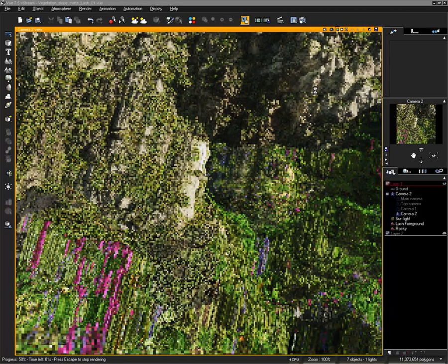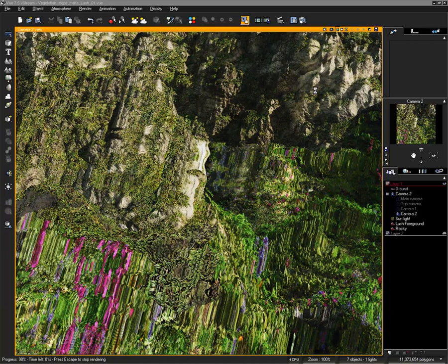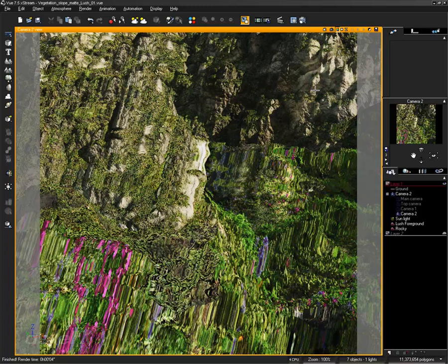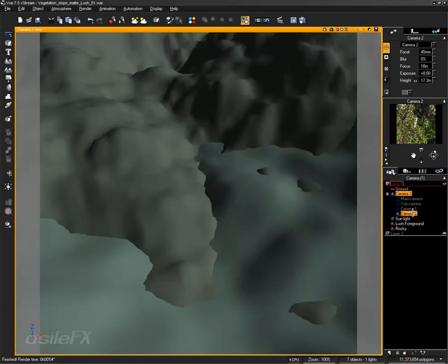And if you find you need more detail in one area, it's really easy just to set up another render of the original terrain, or even with the ecosystem just going through the different stages and steps along the way, the different files. Then you can either remove elements from the scene to preserve the camera and merge it, or one thing I like to do is just to record the position and orientation, and also keep in mind the focal of a camera. And then you can save out either a metanode or just recopy the data over.